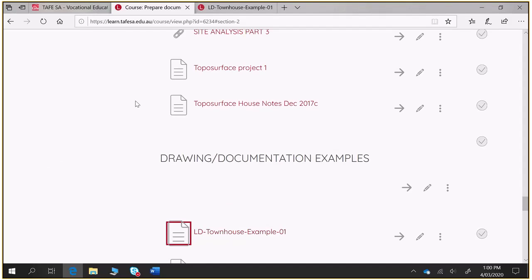No. That sustainability report that I've supplied is a comprehensive building energy analysis. That's what you're going to get whenever you go for building rules consent for a building. There are two options. One option is that you follow the National Construction Code to the letter and you do the deemed to satisfy, in terms of having this amount of insulation here and meeting all the criteria in the NCC for that. Or you can get an energy rating done on the building, and energy ratings don't cost very much because it's a fairly simple process. In that process, you can base most of your decisions on what the NCC recommendations are anyhow, and you'll find that the energy rating just flows from there.